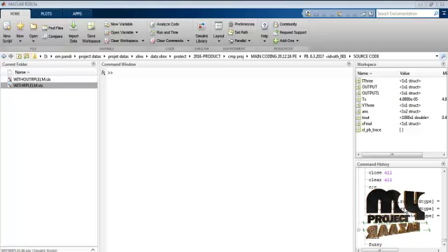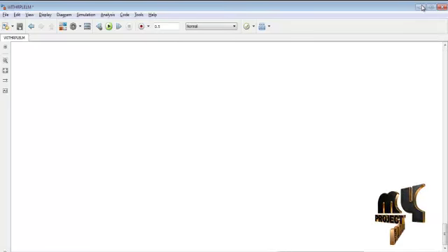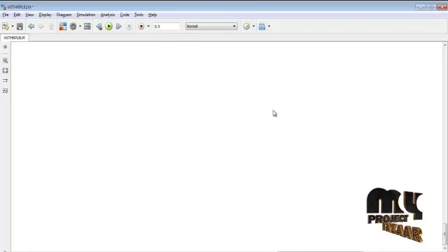Next, we see about the running process of our product. In this proposed implementation, the design is done in the MATLAB simulation environment. First, open a new model file. After opening the new model file, the main window will open. Then the elements are taken from the Simulink library browser. From the library browser, two main blocks are used: one is the SimPowerSystems block, and the other is the commonly used blocks block.